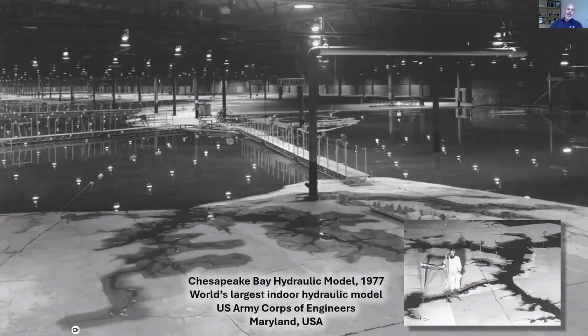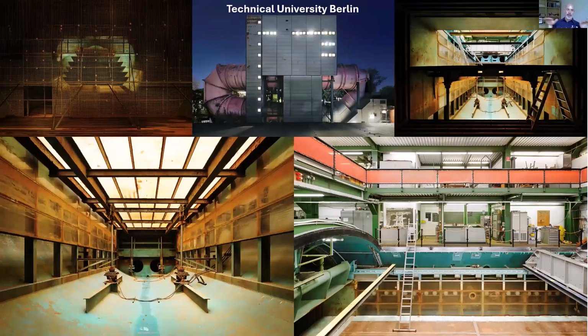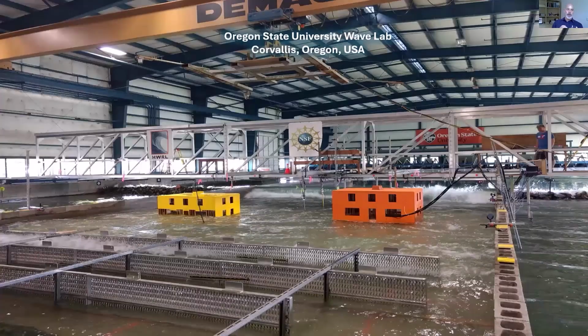Yes, you can, depending on the situation. It's very challenging though. The problem is that you've got to scale the fall velocity of the sediment. And once you do that, you end up with such light sediment that it just wants to float. Okay, and so then you've got to add surfactant. In some cases, the thing it really doesn't do very well is the cross shore. So, you know, if you're standing on the beach looking out, it doesn't get the slope very well.